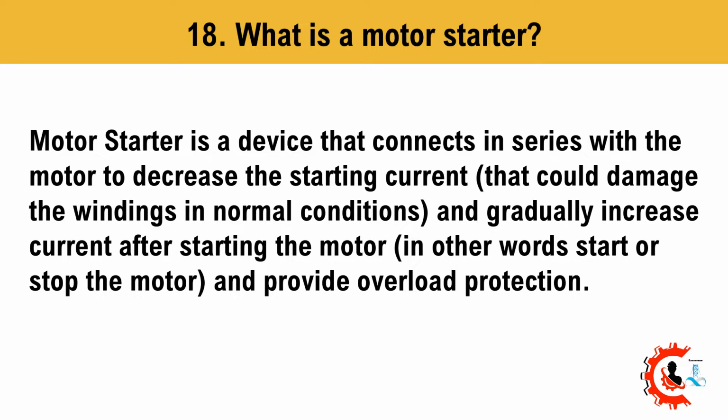18. What is a motor starter? A motor starter is a device that connects in series with the motor to decrease the starting current that could damage the windings in normal conditions and gradually increase current after starting the motor, in other words, start or stop the motor, and provide overload protection.